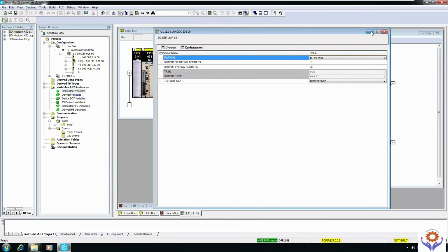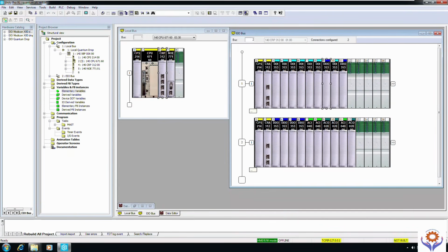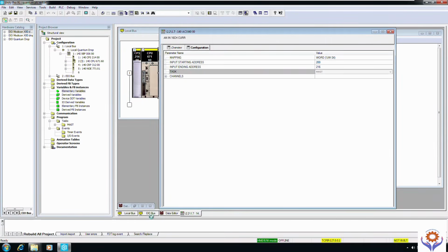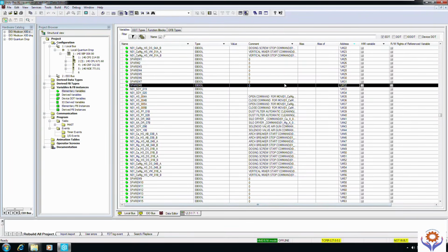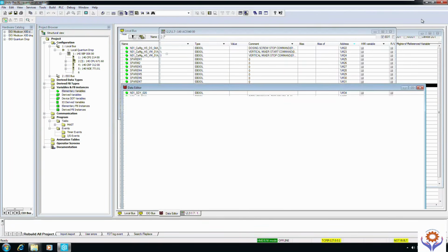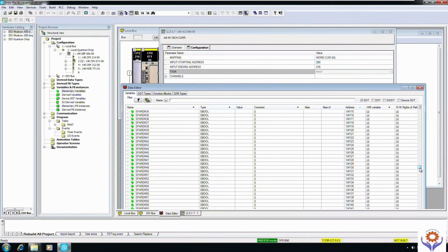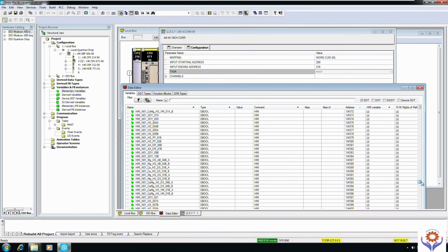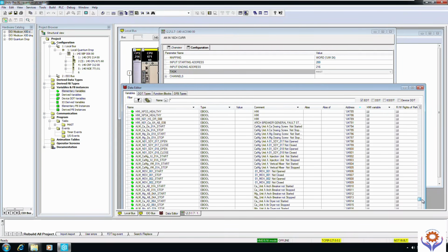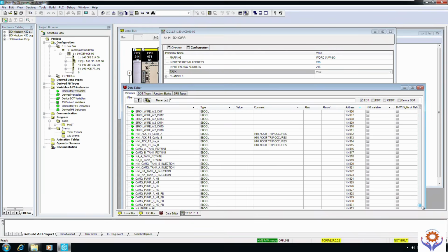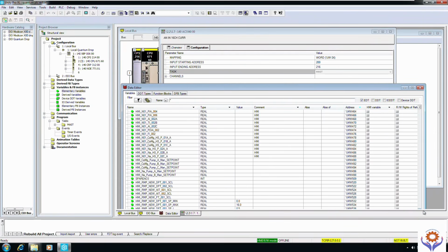Similarly, if you go to other variables, if I click the analog 16 input channel, it is %MW 200. For the 200, if I click, here is %IW 200. If I go further down, I can find the addressing here, %M, and further down you can find percentage here.